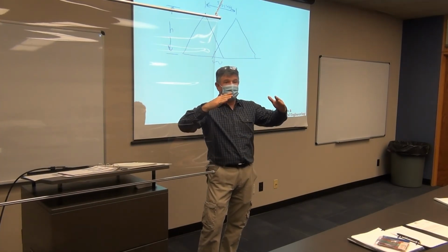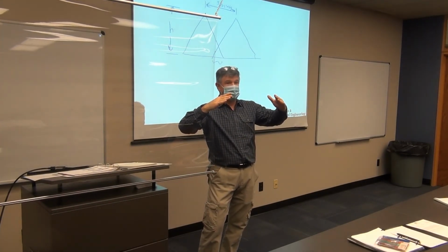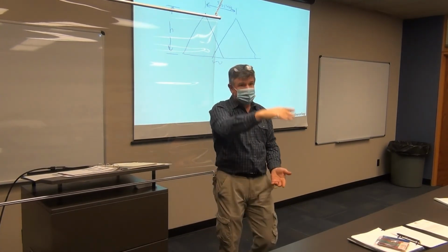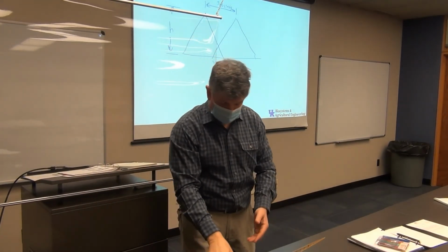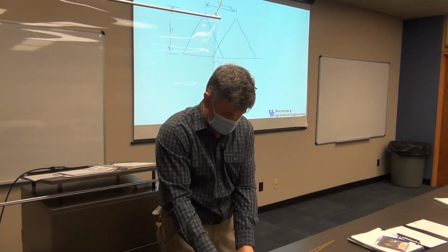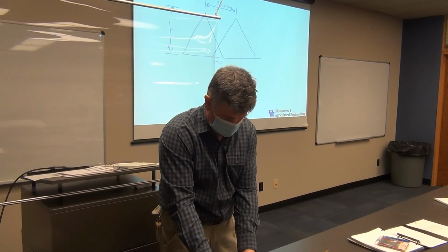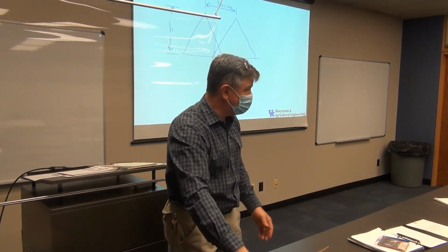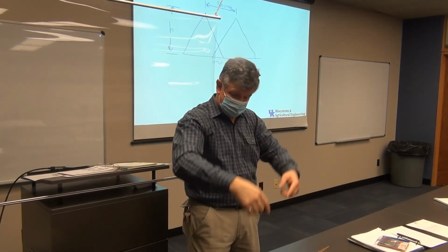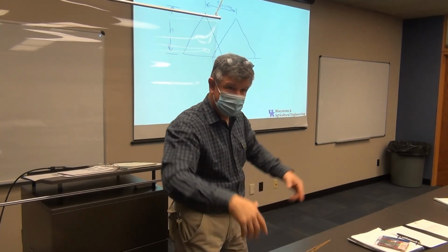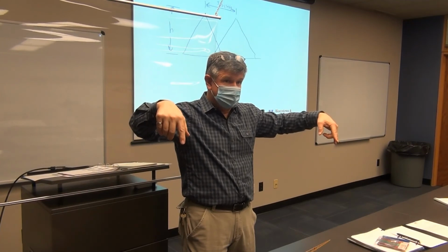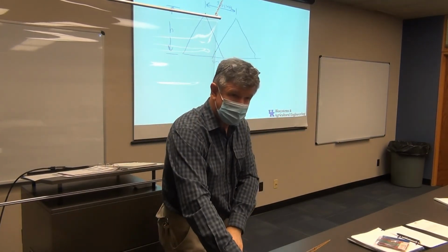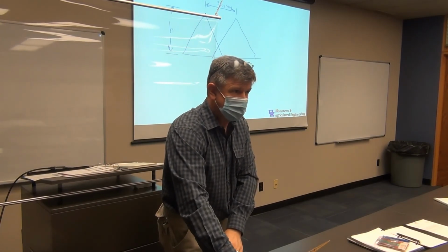So if I buy a different nozzle that wants a different kind of spacing, that's going to dictate how high I need to run my boom. And again, I have hydraulics on these booms that allow me to raise and lower them. So I can run that boom way down to the ground if I need it really low, or I could raise the boom up if I need a little bit more overlap or whatever. I'm not going to change the spacing probably, but what I will do is change that boom height. Okay, do you see the relationship?